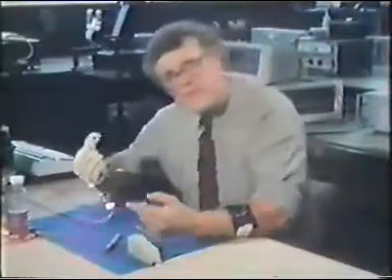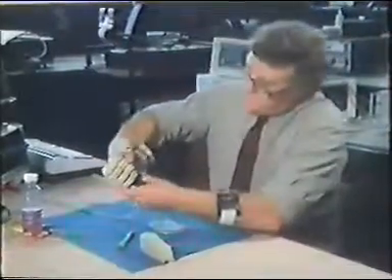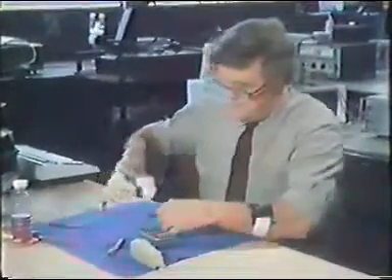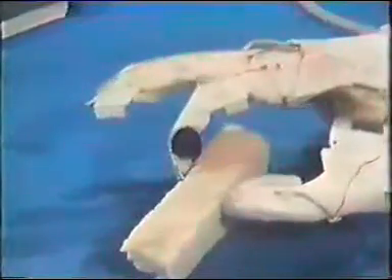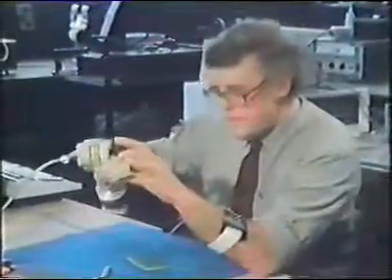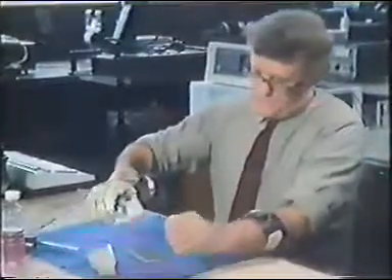There's an even more interesting sensor on this, and that's here in the thumb, and all it is is a microphone underneath this piece of Velcro. And when I want to pinch something in between the fingers, I can pick up this piece of sponge like that, and as I pull this piece of sponge out, or attempt to, the sound is transmitted from this sensor here into the computer. When it hears the sound, it automatically tenses up the hand to stop me from withdrawing this piece of sponge. In other words, it's a complete feedback mechanism. No signal from my hand is affecting it. And I can simply open the fingers and let it drop.